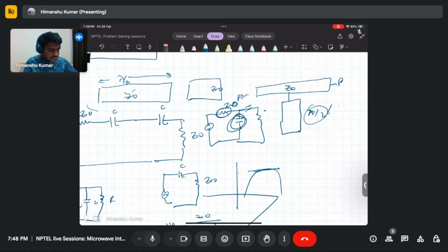If you create this as a short circuit line, this will be shorted, and the node will be grounded to the source, right? So this line can be either a short circuit or an open circuit line. You can design whether you want to connect in shunt or series, based on whether you want a short circuit or open circuit line.